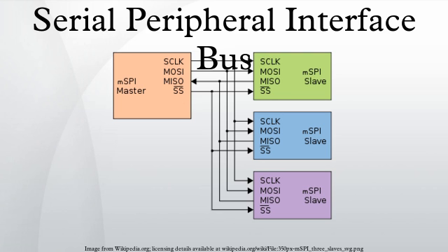Different vendors use different JTAG connectors. Bit strings used in JTAG are often long and not multiples of 8-bit words. For example, a boundary scan reports signal state on each of several hundred pins. SGPIO is essentially another application stack for SPI designed for particular backplane management activities. SGPIO uses 3-bit messages.